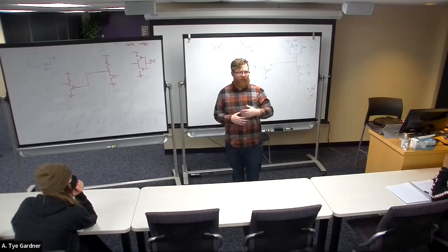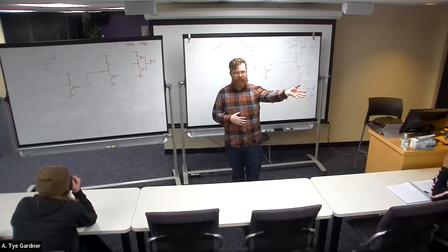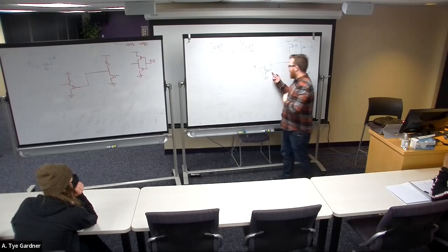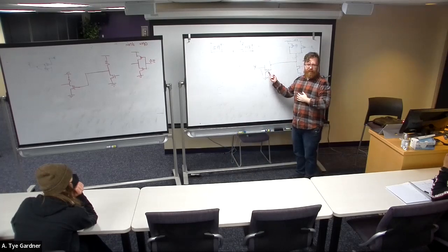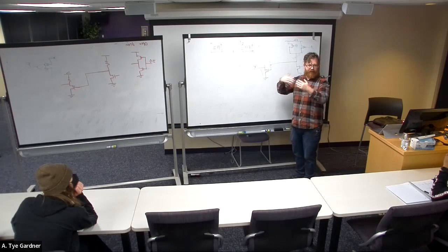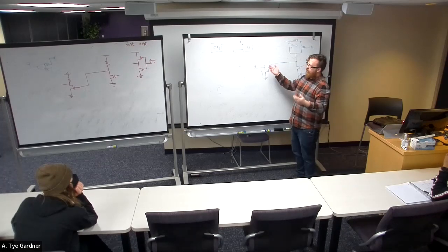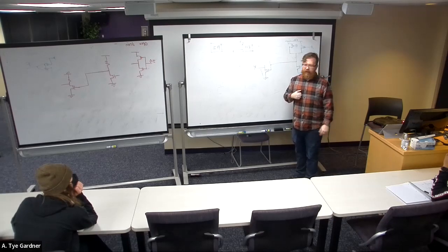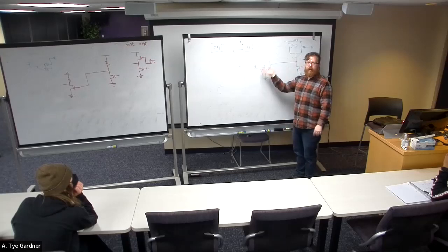One of them will send a message and say, hey, listen up, here's this thing. And then it will go into listening mode, which is to say, turn this off. And so now, if I put a 1 here, it goes to 0. If not, it goes on. And now they can talk back and forth, time sharing one line, both directions. This is why we like open drain. This is all we add to the circuit.